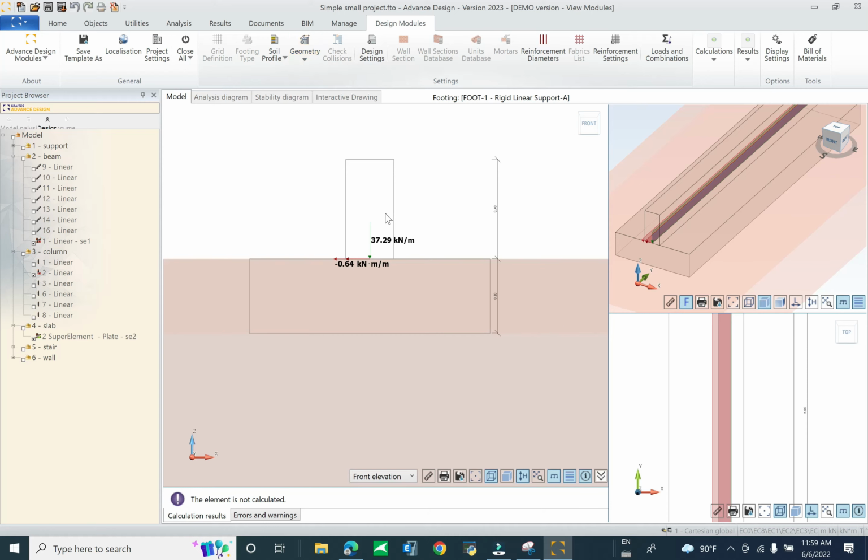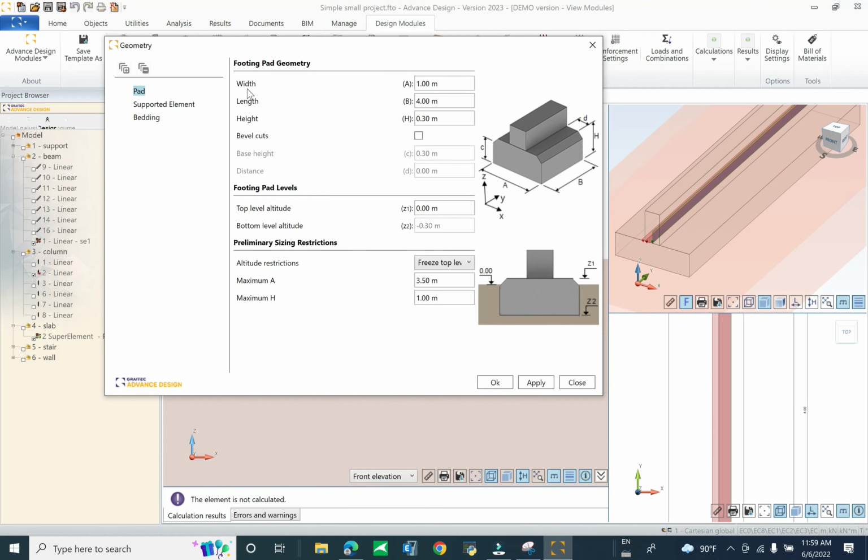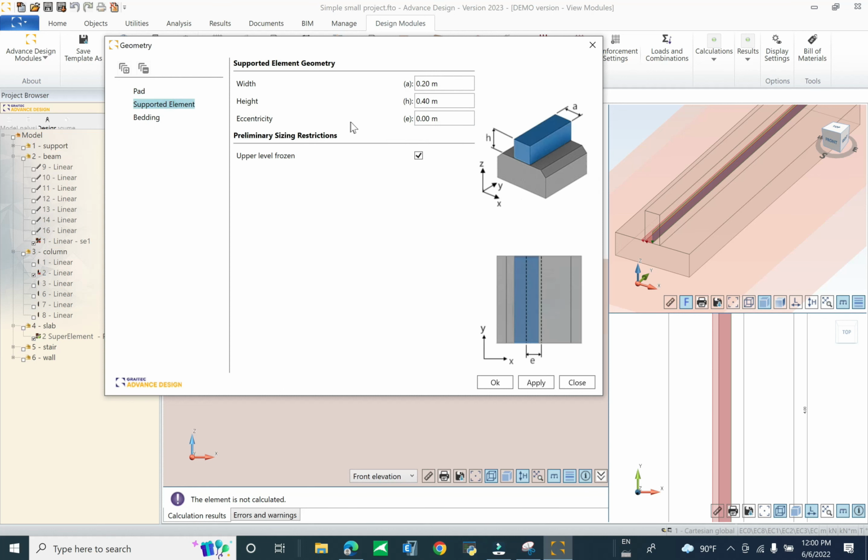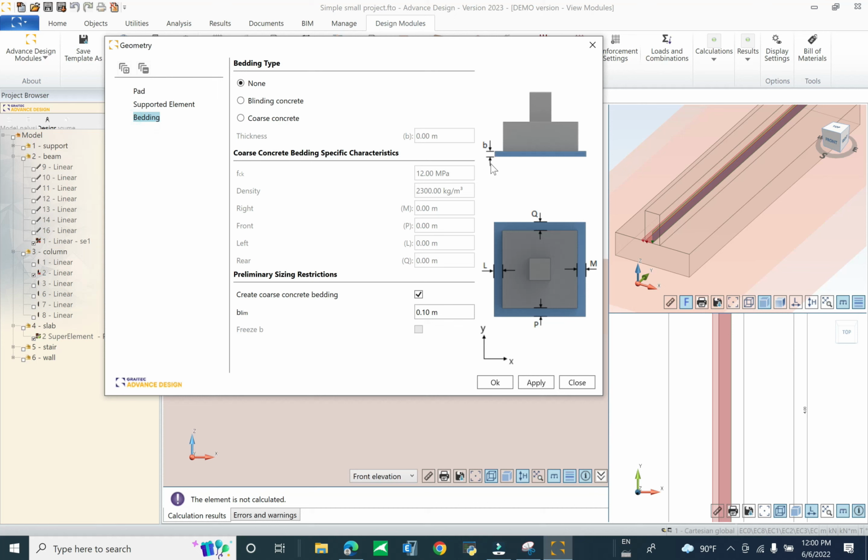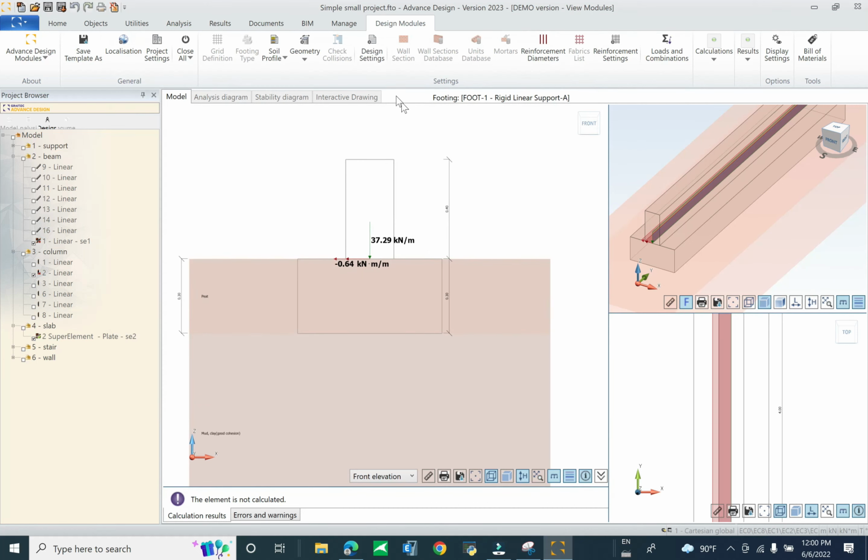And you can correct the geometry, width. By default, it keeps 1 meter. You can change it to 0.6 meter for the width of the strip footing, and length is the default. You need not correct it. And support, okay, splitting, you can include splitting. Now click OK.